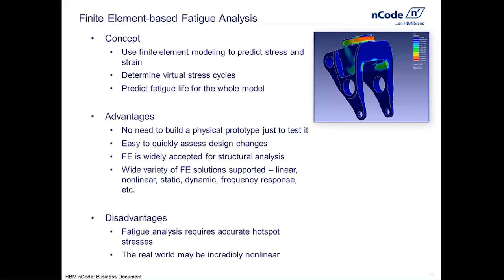The downside is that we have to ensure that the stresses we're getting out of FE are reasonable and correct. If we're going to perform a fatigue calculation, we didn't go into the details of it, but small changes in stress can equal large changes in life. So we need to make sure that the stresses we're getting out of FE are accurate. And that is not always an easy thing to do.